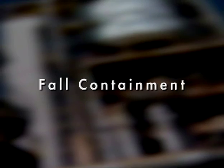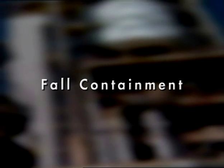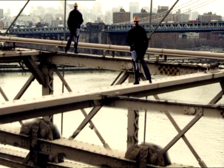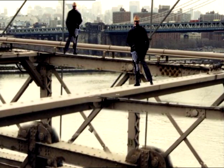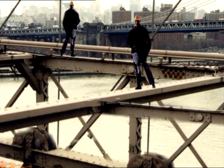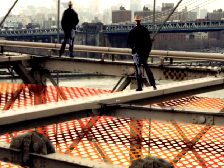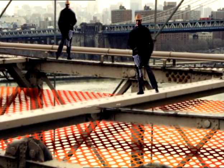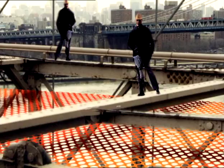Fall containment is not commonly used in the industrial workplace. It's most frequently seen in the construction industry, particularly in structural steel erection, for example in bridge work. Fall containment is the positioning of nets as close to the working surface as possible and is only used when other methods are not practical.